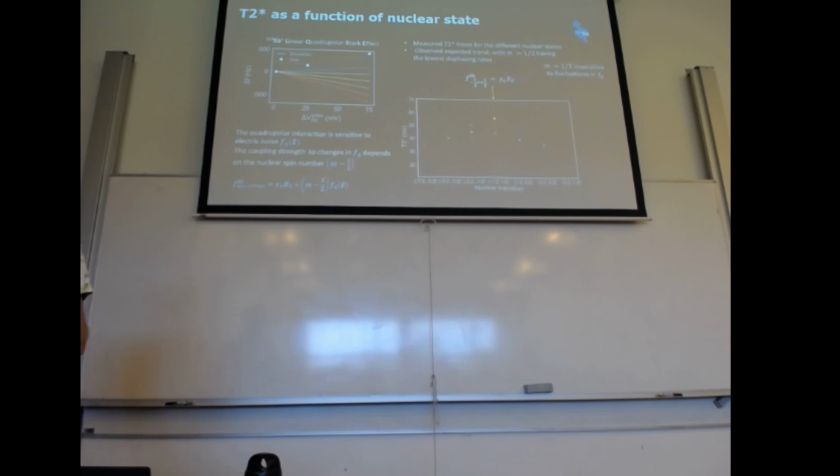Reality is, of course, that this is a nano device. We are working just below the interface, 10 to 50 nanometers or so. So we have interface traps between silicon and silicon oxide, charge noise on the gates, etc. That may affect things a little bit. So we can be certain there is charge noise. But exactly what source affects what property of the system is pretty difficult, I would say, to disentangle. For the phosphorus electron spin, it's a bit easier because it's a faster system. But I must admit that I don't think it resulted in all that much insight into what is the limiting factor. But what can I say? Also for the electron spin, the T2 stars are pretty good.